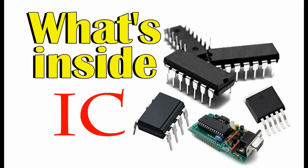DSPs can be designed to perform fixed point or floating point arithmetic, depending on the specific application requirements. Fixed point DSPs are often used for cost-sensitive applications, while floating point DSPs offer higher precision at the cost of increased complexity. Parallel processing. Many DSPs feature multiple processing cores or execution units, allowing them to perform multiple calculations simultaneously, which is crucial for real-time processing.